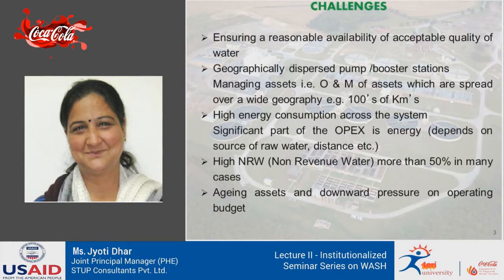And you have to maintain the operation and maintenance spares for those booster pumps and all the mechanical items. And then you have high energy consumption across the system, which plays a very vital role, because energy efficiency is becoming a very critical thing these days. It's a part of the OPEX, that is the operating cost. So if your system is energy efficient, the system will run for a long time.